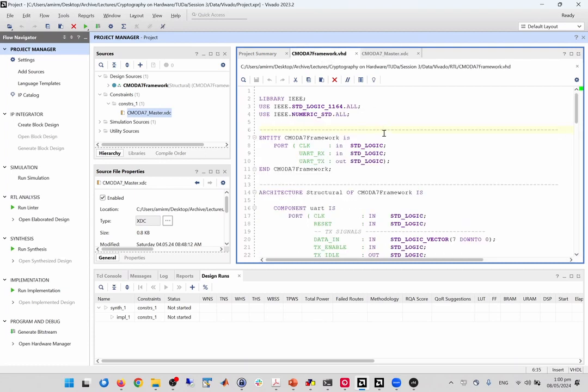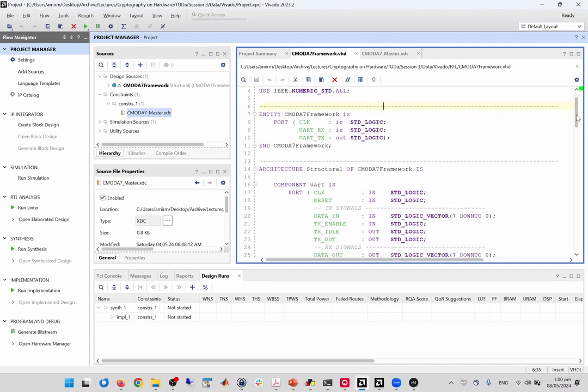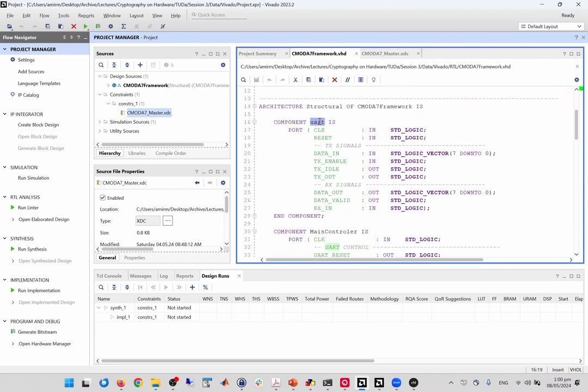Yeah, these are just the pins. You need a UART module inside your FPGA to communicate. For that, I provided a UART module for you here with the clock, reset, data in, transmit, and receive. This UART module works on a single byte, meaning for every single byte you need to communicate with it. You cannot configure it and say, okay, receive 10 bytes. No, it's just one single byte, and then you have to receive every byte and save it in a register.